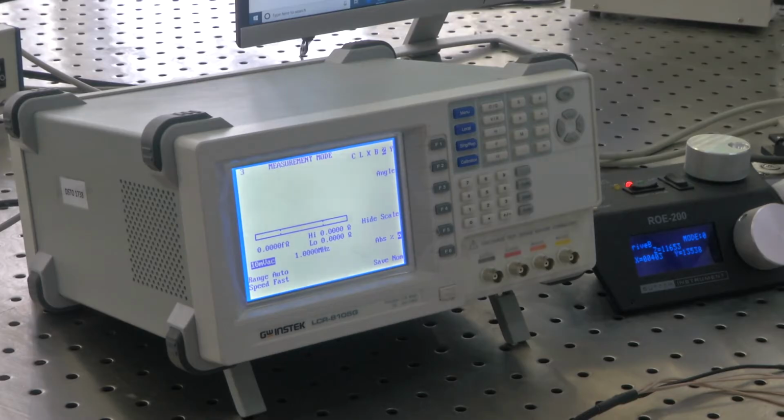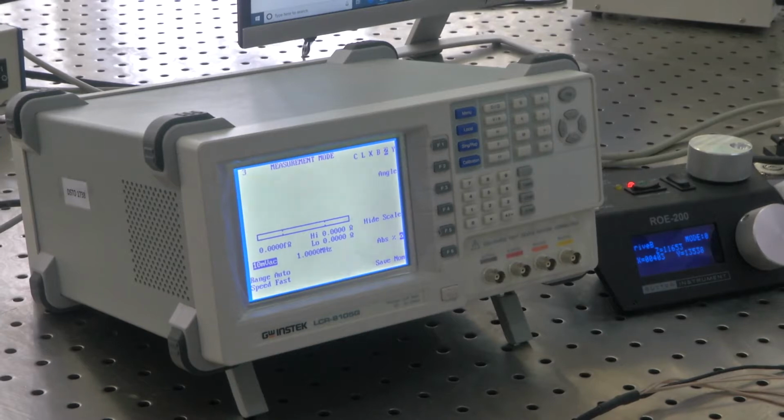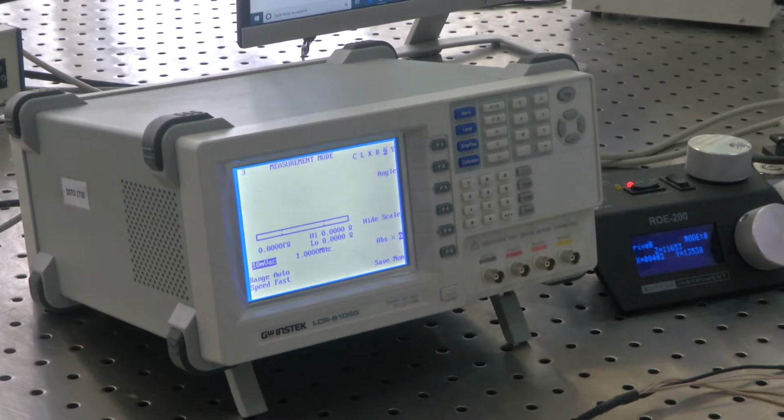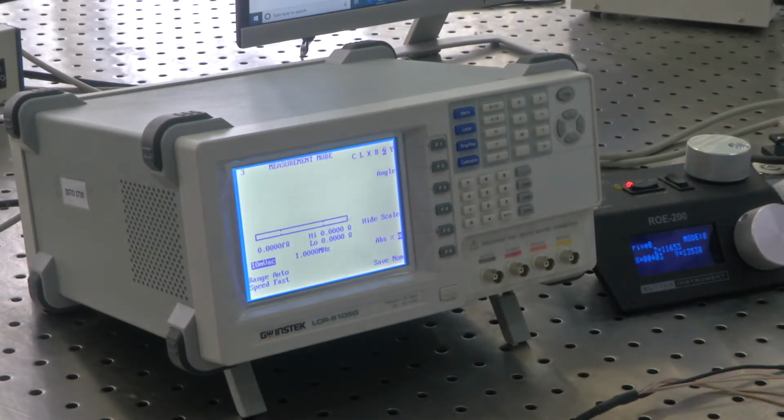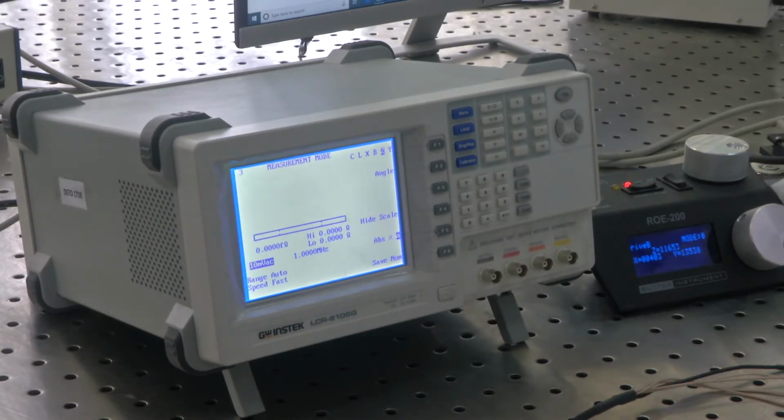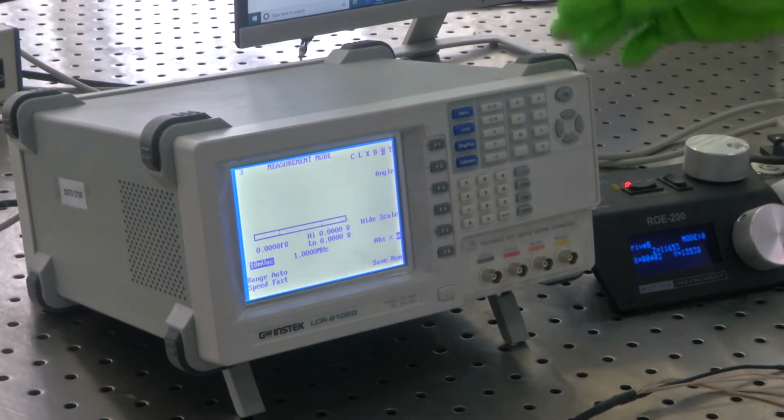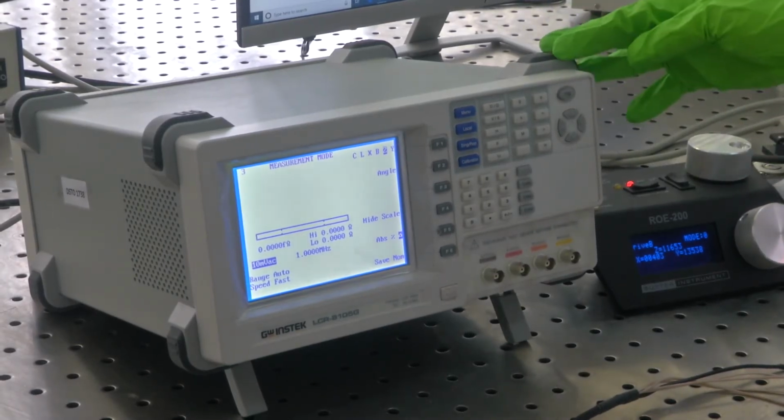These are the four key specifications of an impedance analyzer: the frequency range, the impedance range or the impedance values that we can measure, the accuracy of the absolute impedance, which consists of both resistance as well as reactance values, and the phase angle. If we know the absolute impedance and the phase angle, then we will be able to calculate the reactance as well as resistance components also. These are the key specifications of the impedance analyzer.